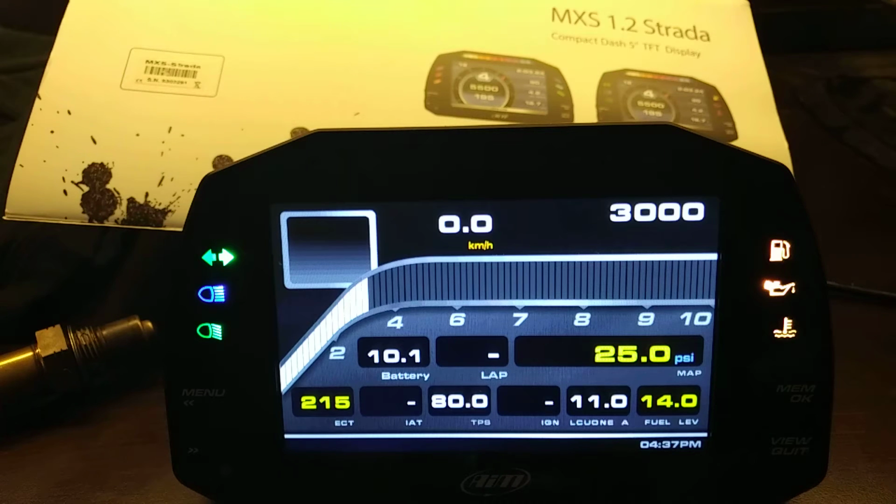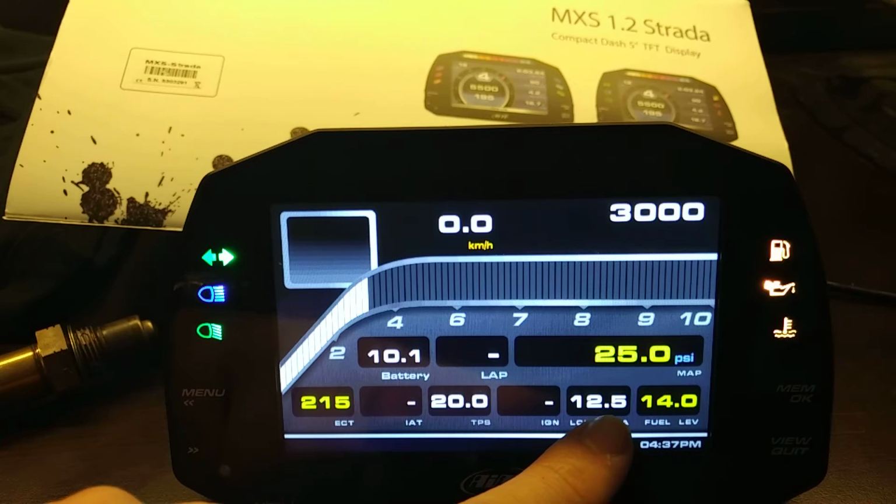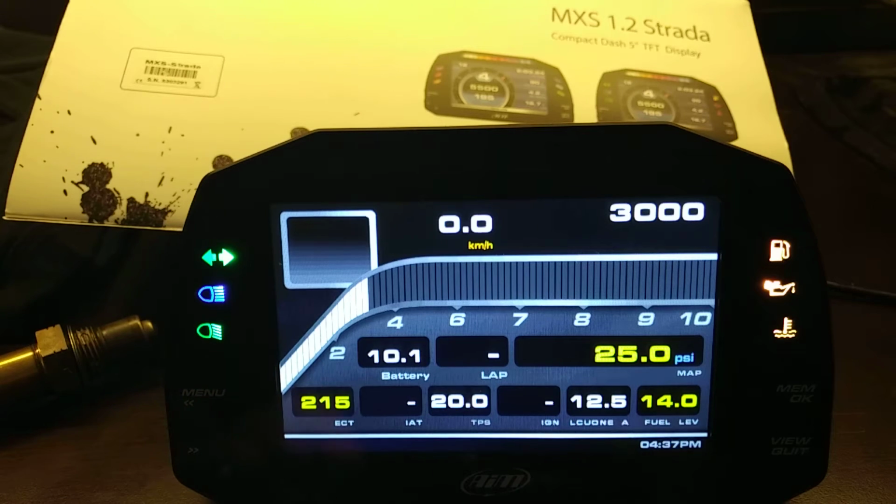However, if we go back to the warning state, let's say 12.5 to 1 AFR, and we remove the throttle position, obviously under partial load, let's say we make the throttle position 20. Under partial load, closer to stoichiometric, leaner fuel ratios are allowable, so the alarm will go away. So you can see here that that yellow illumination went away.